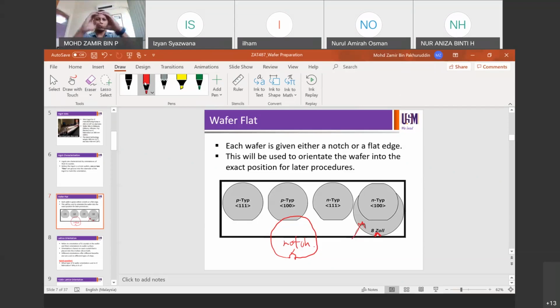It cannot go like that. It cannot be diagonal. It cannot be random. It has to be like this, perfectly like this. For example, the lithography process, some other processes as well. The moment you have the notch, what it does in the fab later on is home alignment. They call it home alignment, or some call it zero alignment.